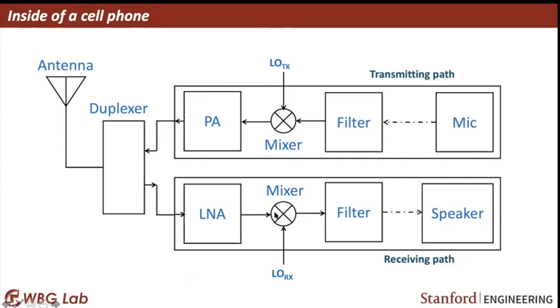What the mixer does is it takes down the frequency from the high frequency of 4G or 5G to our normal frequency range. So it just demodulates it, right? It removes the carrier signal and takes down our message, and then it goes to different filters, different baseband processors, and then finally it comes to the speaker. So that is the receiver path for a signal.